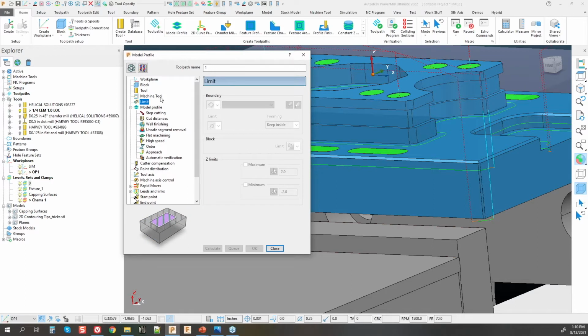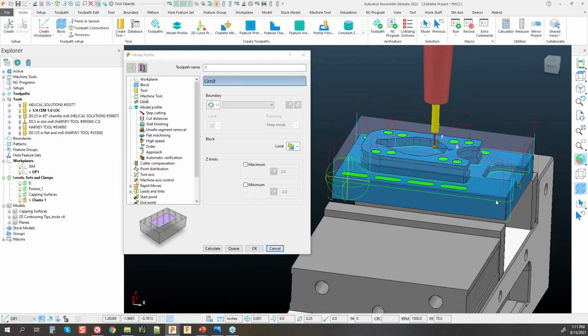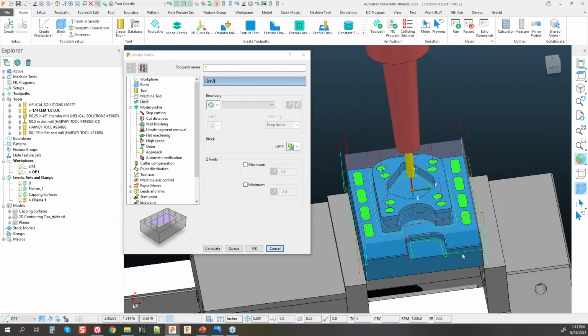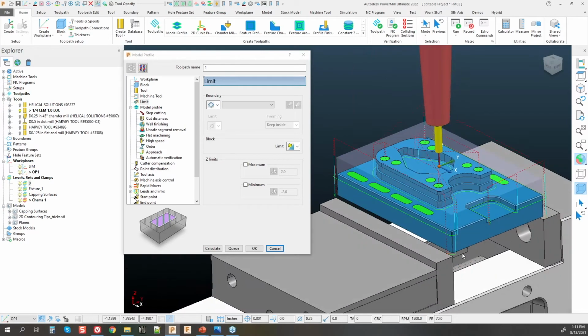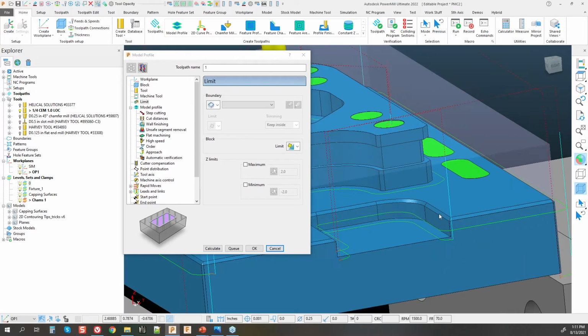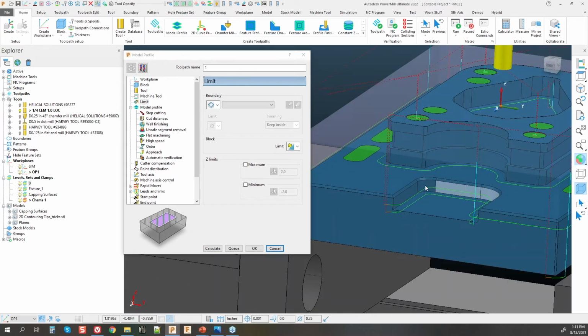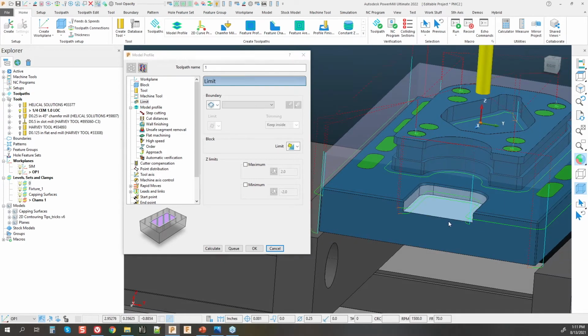Even when we have our limits set to outside of our block, as I do with my defaults, that still will cut the toolpath at specific spots. You can see there are some regions here that are allowing it outside of the block and some that are not. However, if we just open up the block a little bit, we should be able to calculate that area. One reason why this is very popular with users for a very long time is that we can be a little specific with this. If we shrink our block down to a specific region, I'll select a few surfaces here. I know I should put paintbrush on, but I'm not going to.